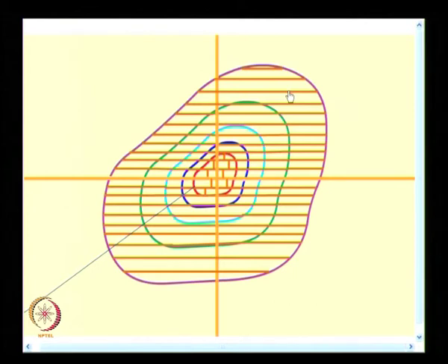And I have also cautioned, as experimentalists, people develop methodologies to extract this. My recommendation for using brittle coating is to find out the principal stress direction. It is very simple. The moment you get the cracks, they indicate the principal stress direction.